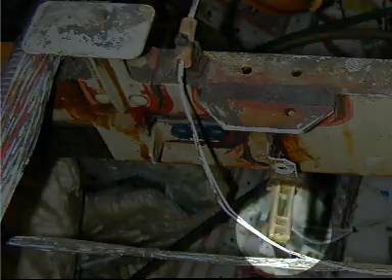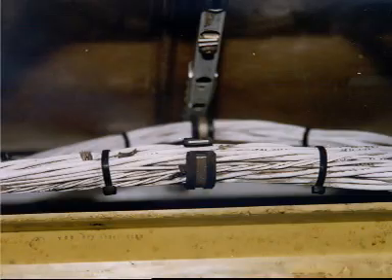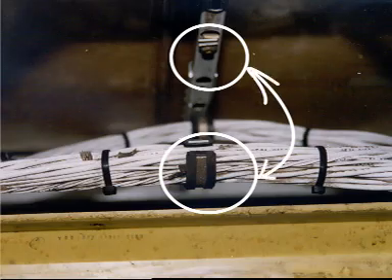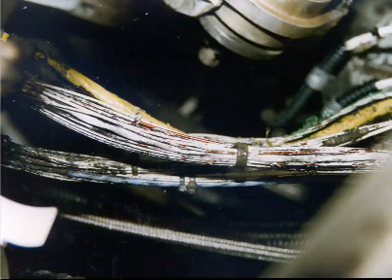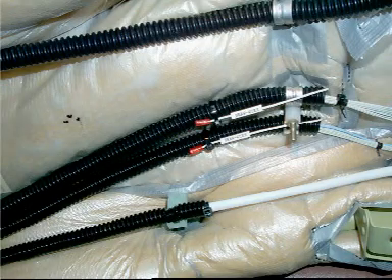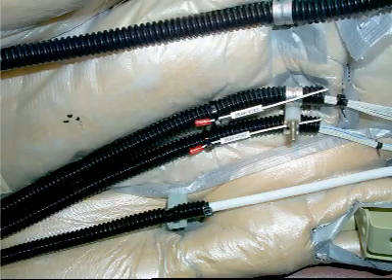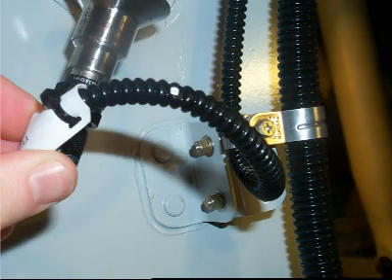For the supports, do a check of protection, attachment and rupture. Check there is no deformation and it is in a correct position to avoid chafing, for example. For the conduits, check they are not flattened, check they are in the right position and allow draining.